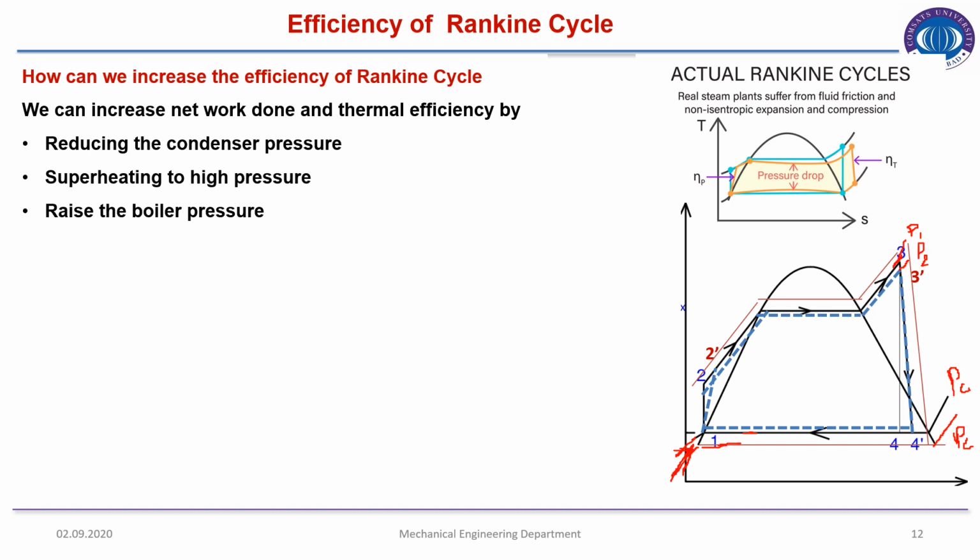So that is a low pressure line, and that solid is a high pressure line. To increase the area enclosed, the area enclosed represents the value of available energy, and the area that is beneath here, if we join these lines with the dotted line, is unavailable energy. If we reduce the condenser pressure, some of that unavailable portion will be included in this available energy portion.